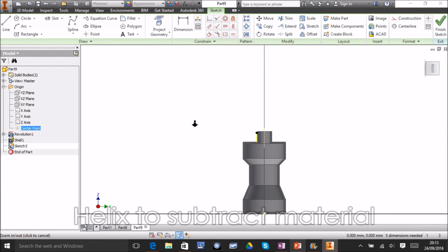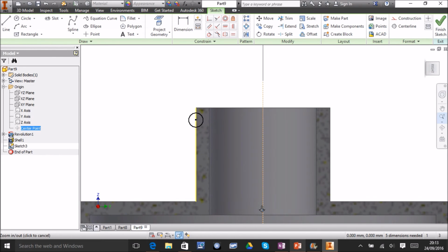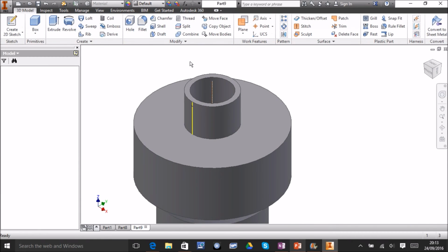And then say I wanted to make the opposite piece, like the lid for the bottle. I've not made a separate bottle lid, but this will show you the idea. Instead of, if I zoom in on this, with my bottle this time, instead of trimming the bit of the circle on the inside, I'm going to trim the bit of the circle on the outside, but it's exactly the same setup otherwise. Finish the sketch.